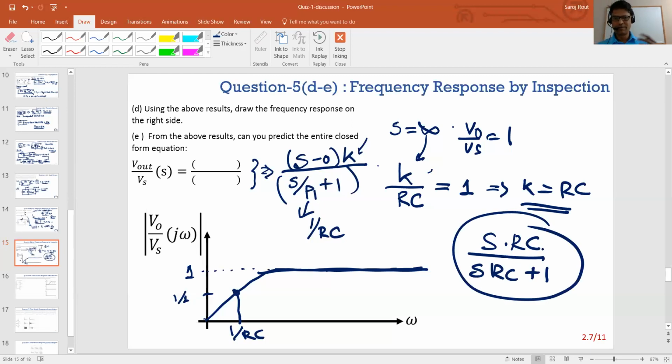So this is, again, trying to find a closed loop transfer function by inspection without actually writing the node equations. Like I said, a lot of times when you're doing design, it'll be very impractical for you to write node equations, and you have to do it by inspection. You'll do it hierarchically. Sometimes you'll break the circuit into a couple of pieces. So this is a tool we use as designers a lot, so it's something good to know.